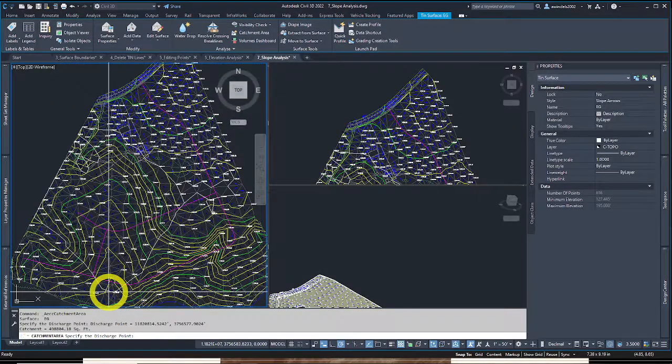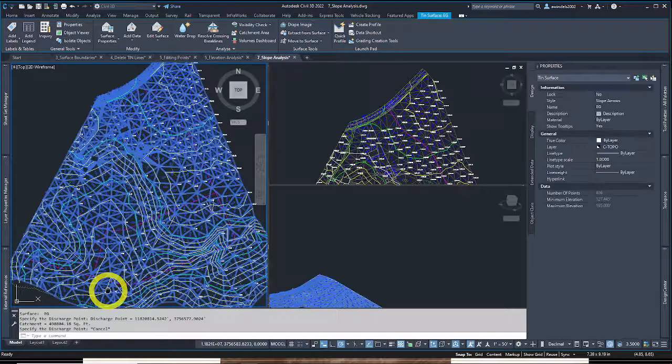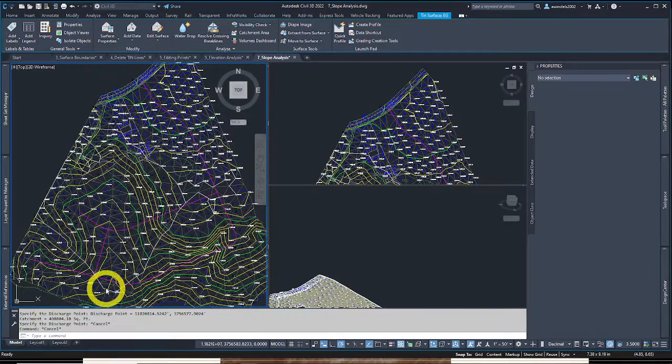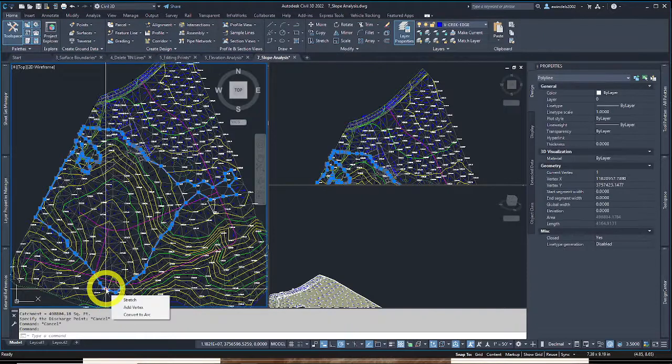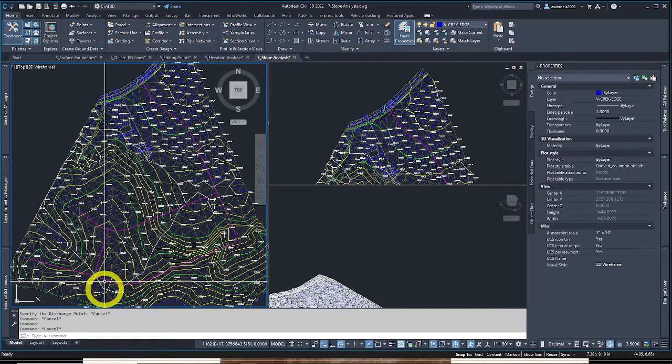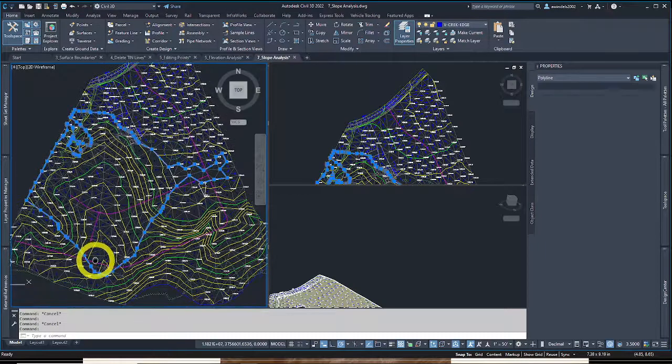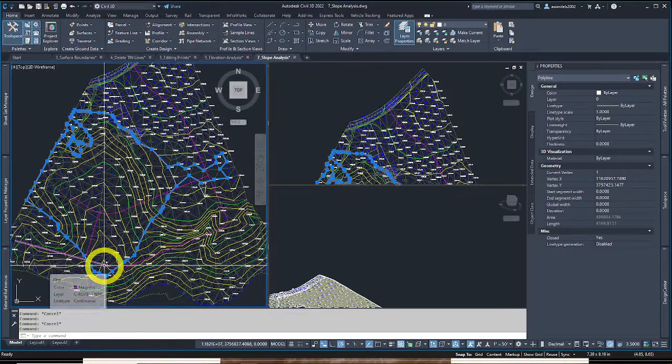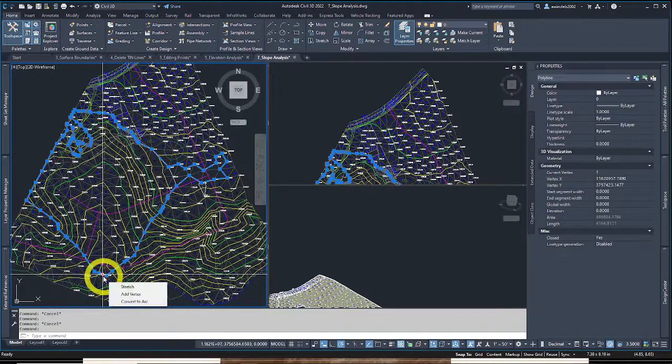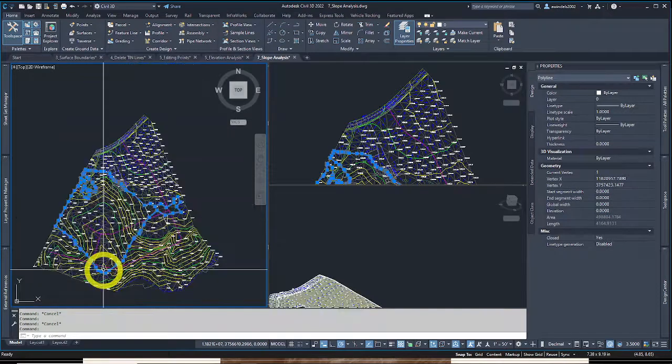So this is more of a low zone to the bottom of a ditch or flowing downhill. This area could potentially get this entire catchment area, this entire hydrology, this 2D and/or 3D dimensional area. So theoretically right here, if I had a structure, let's say everything in that theoretical zone could flow into it. So you might not want to put something prone to a flash flood right here in this existing. That's a lot of surface area that could drain to it theoretically. So that's the catchment area tool.